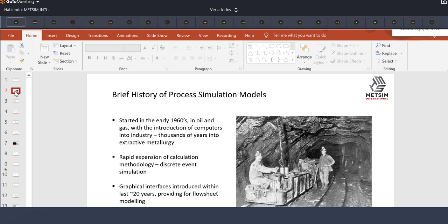That's what a process simulator comes with, our first principles. You then start calibrating based on how equipment and material performs. For example, flotation. Flotation is not a simple thing to say, well, if I have so much copper, so much lead, and so much zinc, this is what will be recovered at this particle size. We still need to run those tests because you may take those same parameters on a completely different ore type and they flow completely differently. So that's where the calibration really comes from.